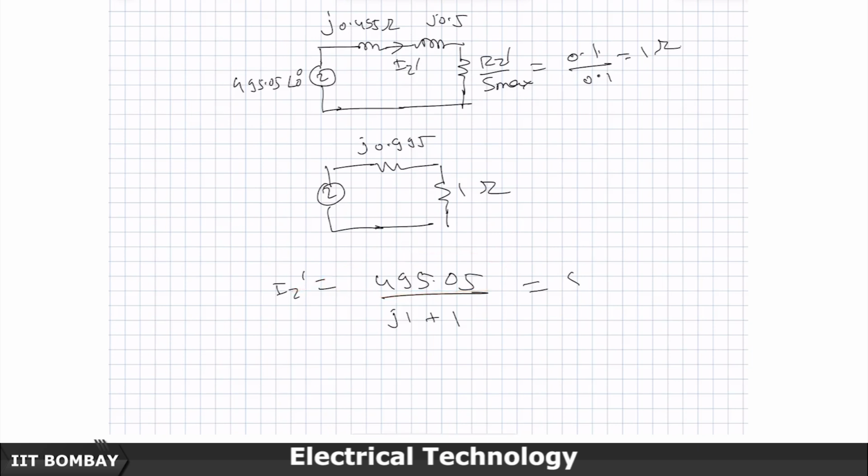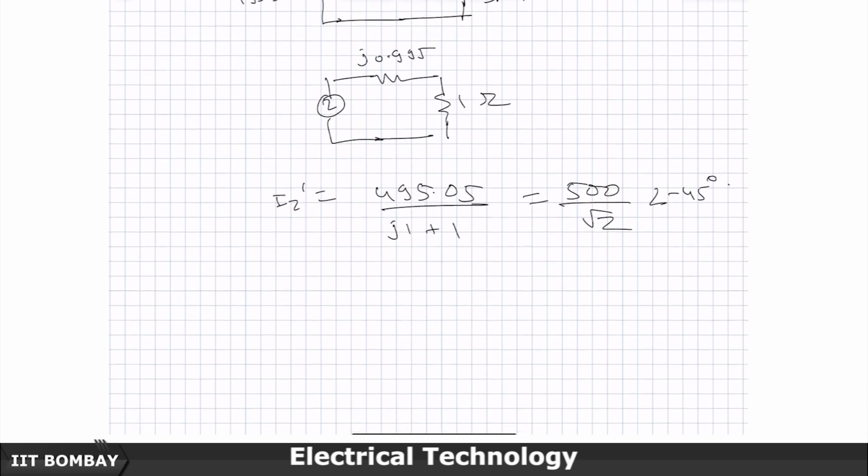And even this 495 point, I will write it as 500, just to keep this like solving the approximate circuit. So, 1 square plus 1 square is 2. So, the magnitude of the impedance is root 2 and the angle is minus 45 degrees lagging.